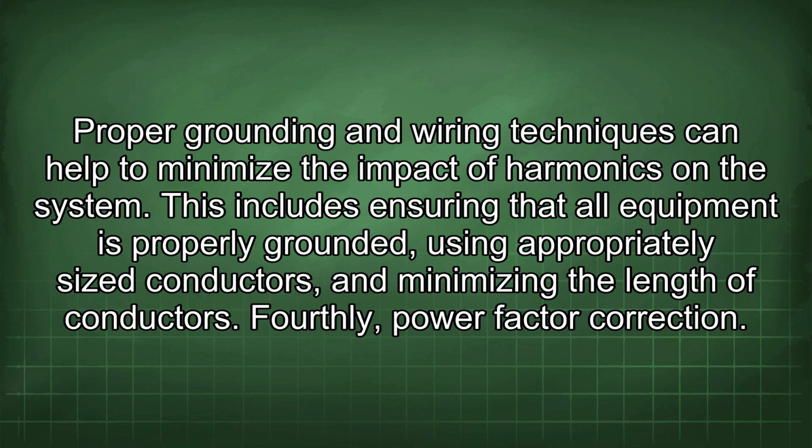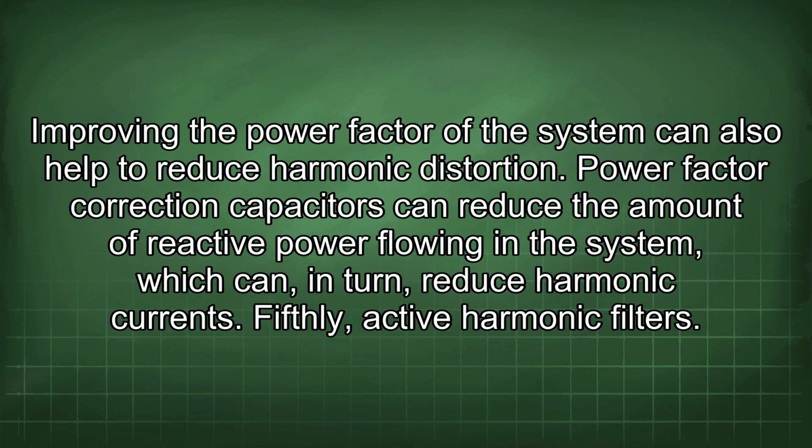Fourthly, power factor correction. Improving the power factor of the system can also help to reduce harmonic distortion. Power factor correction capacitors can reduce the amount of reactive power flowing in the system, which can, in turn, reduce harmonic currents. Fifthly, active harmonic filters.